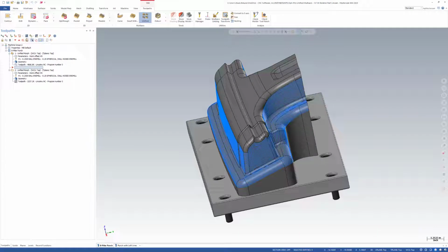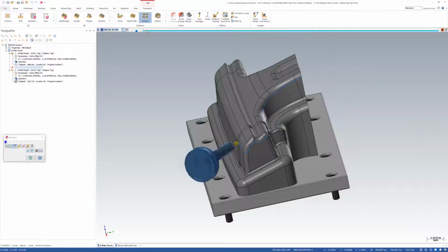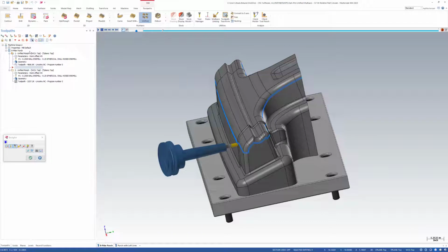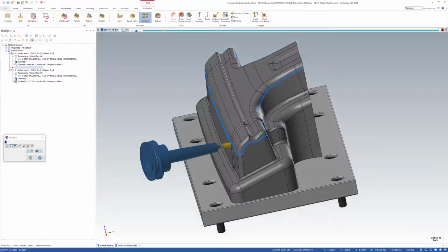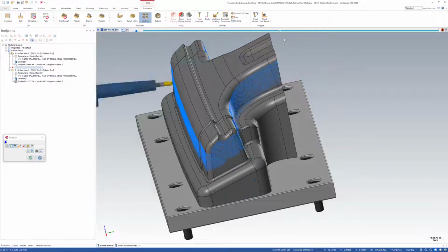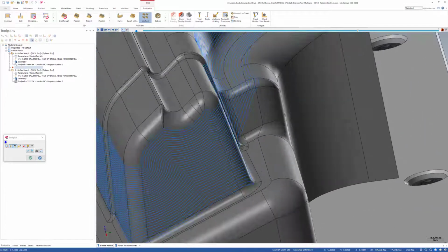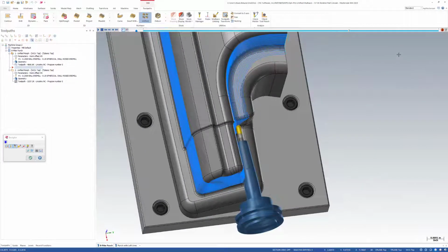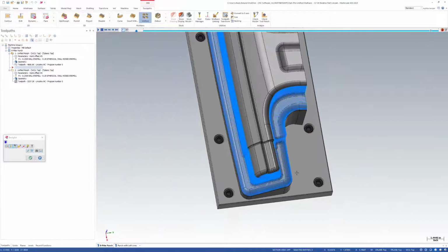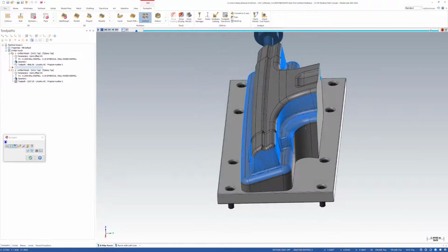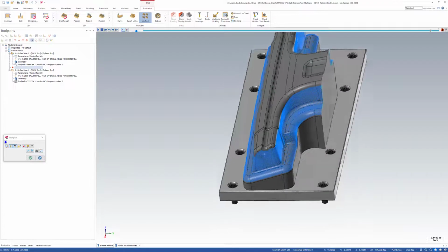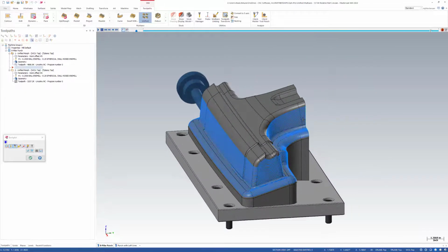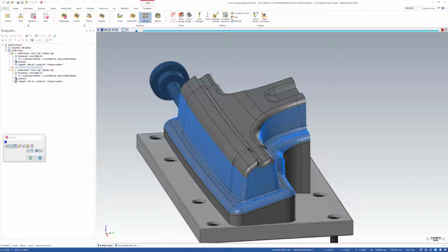So the first operation here is just set normal to surface, right? So the tool tilt motion is pretty crazy. You'll notice this is an old Morph Toolpath that was adapted up to unified by opening it in 2023. So this is essentially just a morph between two curves. But again, normal to surface is not going to work here. And I would admit this is a pretty ambitious toolpath, where tool axis control is not going to be very simple. I can't select one chain I want to drive to, or one point. I'm really kind of forced into using collision control to avoid these collisions, right?